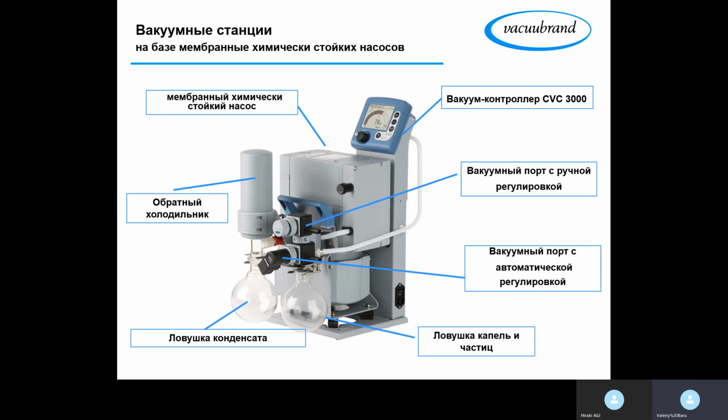We were evaporating about 6 liters during the test runs after the installation. And when we evaporated 6 liters of THF, we collected about 200 milliliters of THF in this receiver. So imagine you have a puddle of 200 milliliters of THF under the vacuum pump.